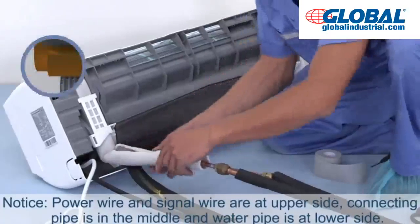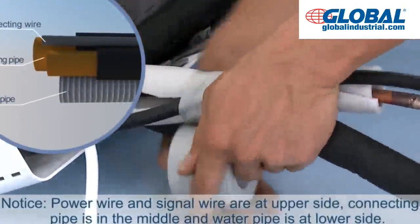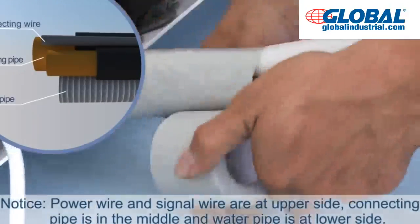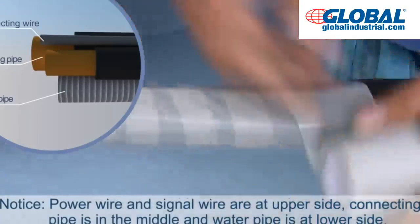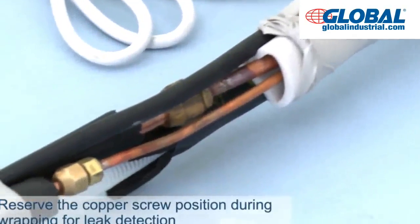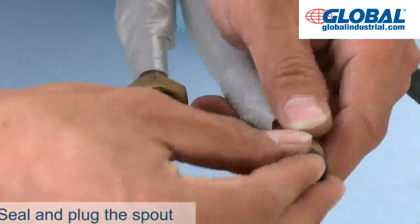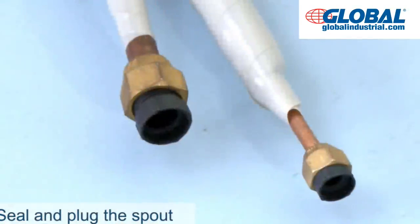Wrapping is conducted in order, where power wire and signal wire are at upper side. Connecting pipe is in the middle, and water pipe is at lower side. Reserve the copper screw position during wrapping for leak detection. Copper pipe should be sealed to prevent dust or foreign materials from entering when going through the wall.